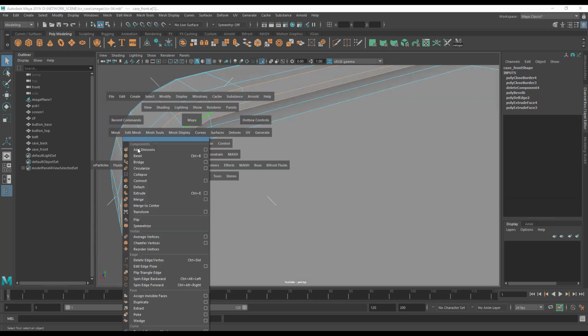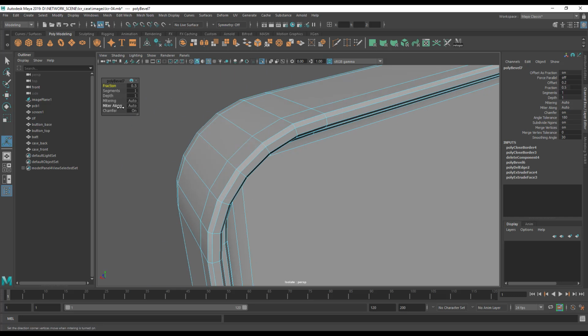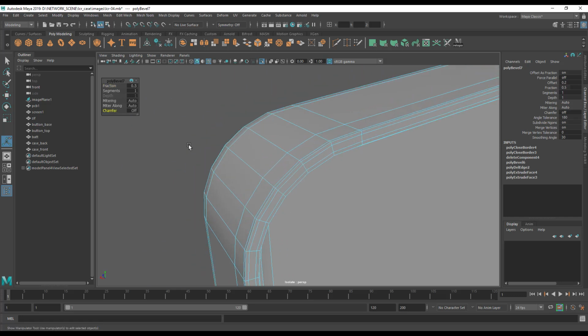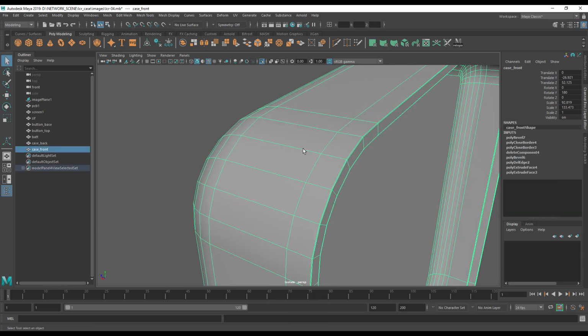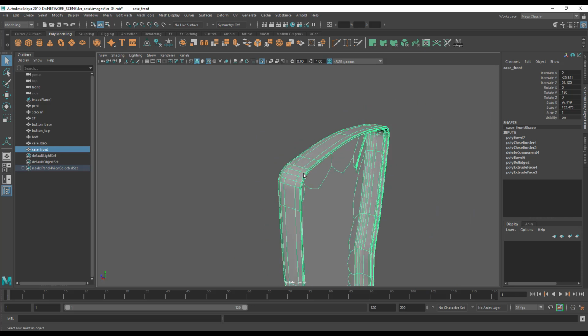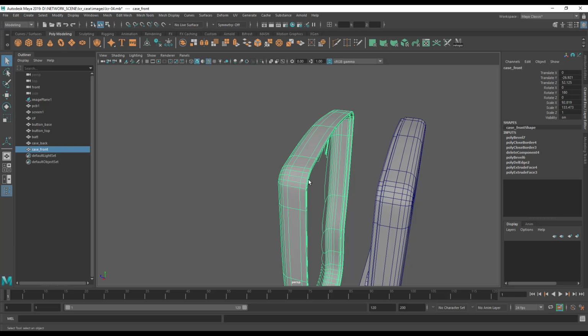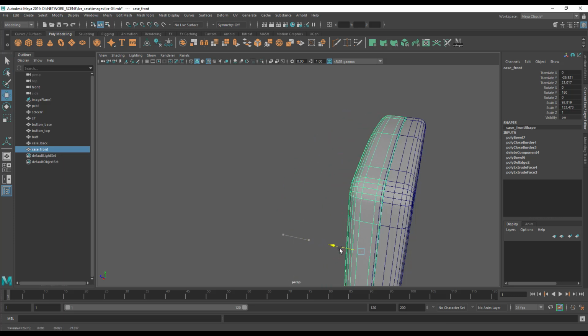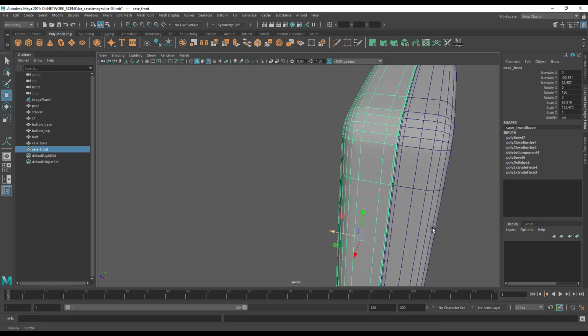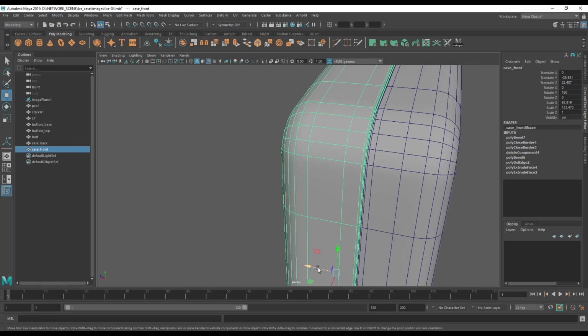So just go up to Mesh Bevel, and we can turn the chamfer off, very important, and set the bevel fraction to 0.1, and that should be identical to the other bevel. Okay, let's smooth this case. Hit Control 1 on the viewport here. Let's smooth this one and double check that they fit together. And they seem to fit together absolutely perfectly.